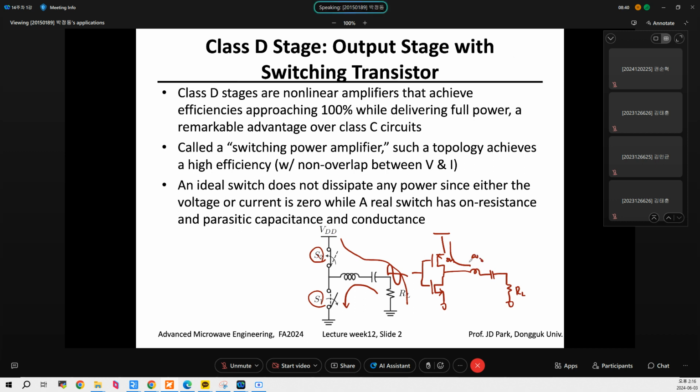So at other frequencies, this is large, which means at the output, the harmonic component is suppressed, but the fundamental signal is just going through this series reactance term, I mean, series resonance circuit.